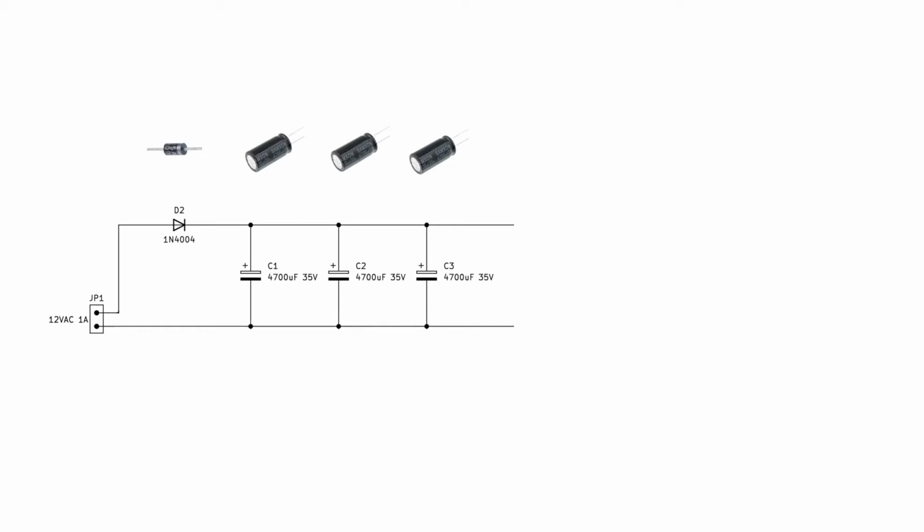A voltage drop of about 1 volt is caused by the rectifying diode. Keen viewers will have discovered that these numbers are not exact, but they are close enough to get the idea. Anyway, we must reduce the voltage a bit and de-ripple the signal even more. That smells like we need some more electronics to be added to our schematic.